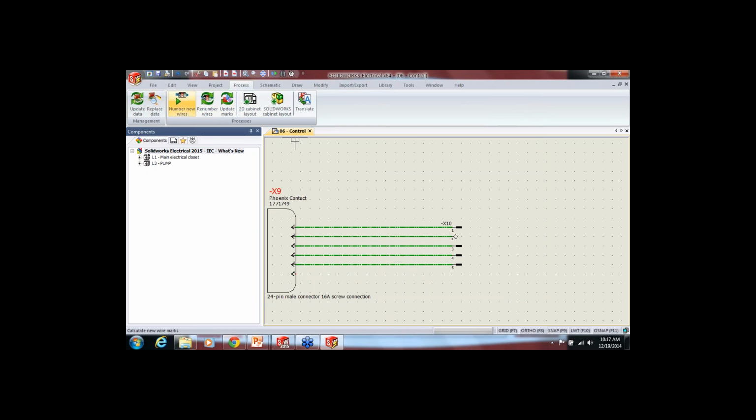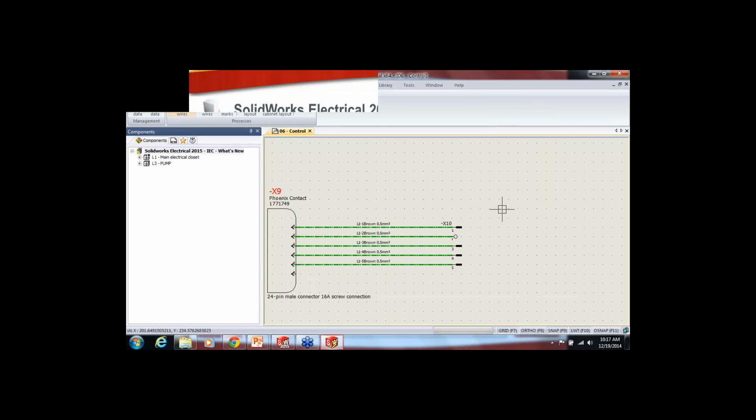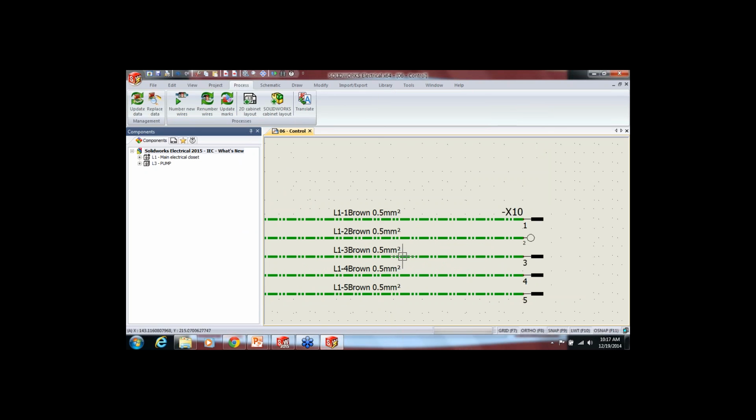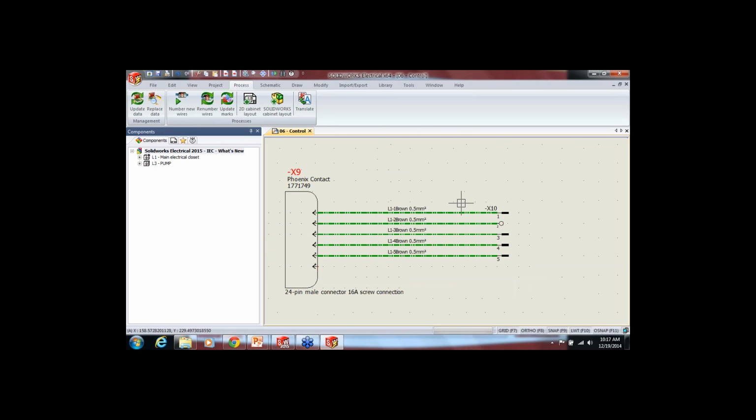And now I'll just renumber the new wires. Yes, without modifying. And now my label's got, using that formula we just said to use for the location, and then the number, equipotential number, and the color, equipotential color, and the cross section, I think, and I don't remember what all else, but anyway, we're using that new formula there to label these wires.